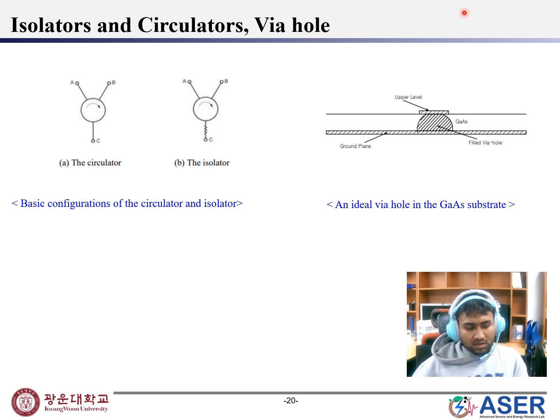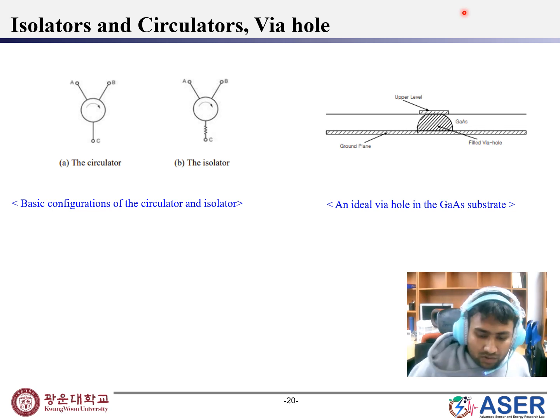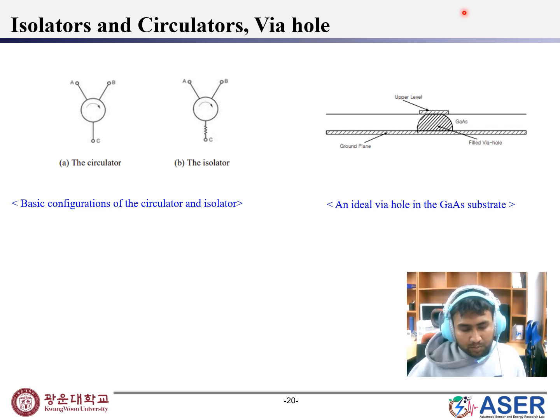These are so-called through wafer holes or via holes, and can be used in a broad range of applications such as two-dimensional packaging, three-dimensional packaging, microelectromechanical systems MEMS, or multi-chip stacking. Both microstrip and backside grounded coplanar waveguide technology require via holes either to provide microstrip short circuits or to tie the upper and lower ground planes of the coplanar waveguide together.